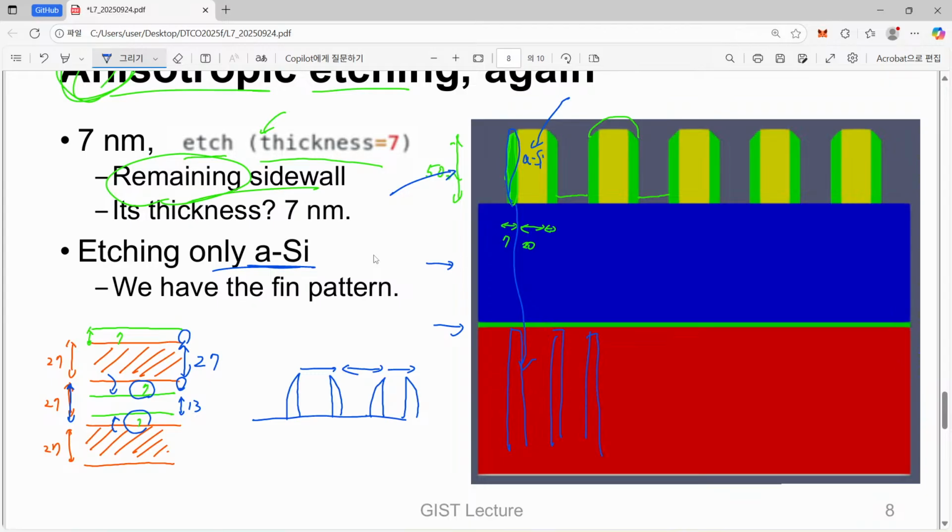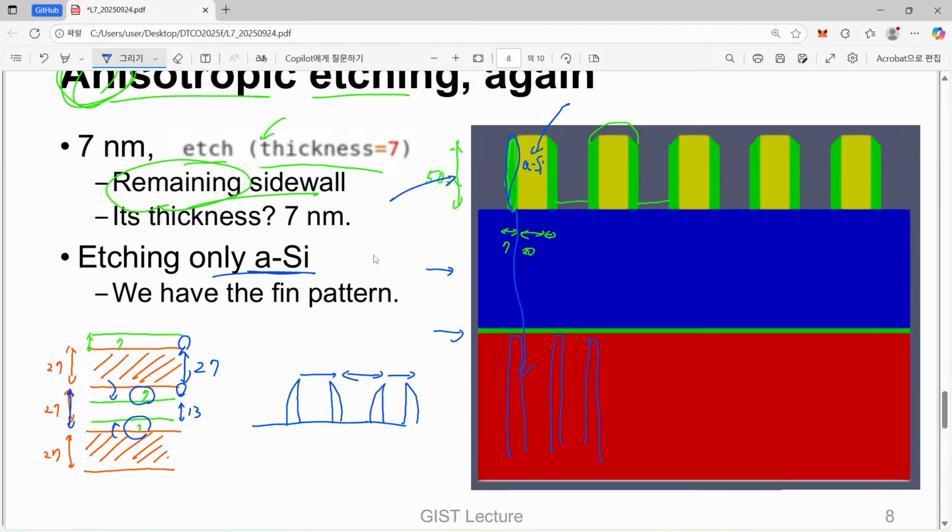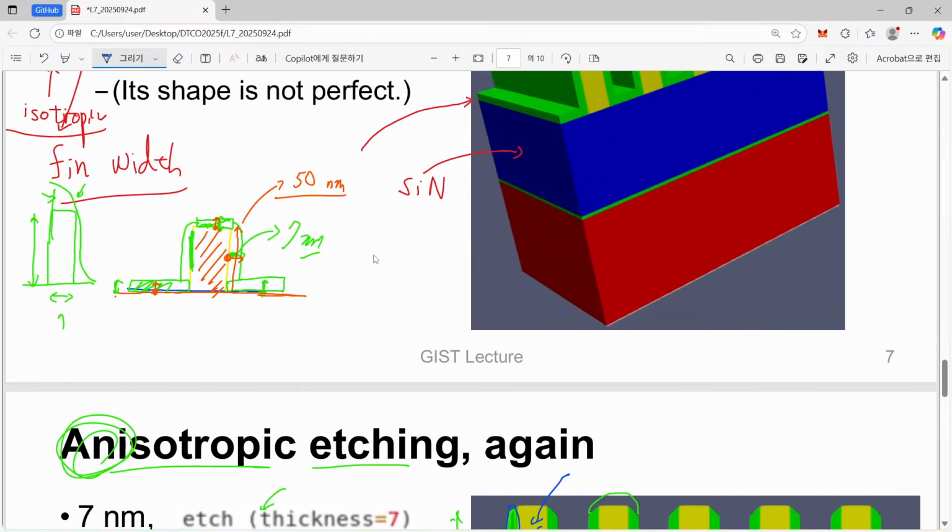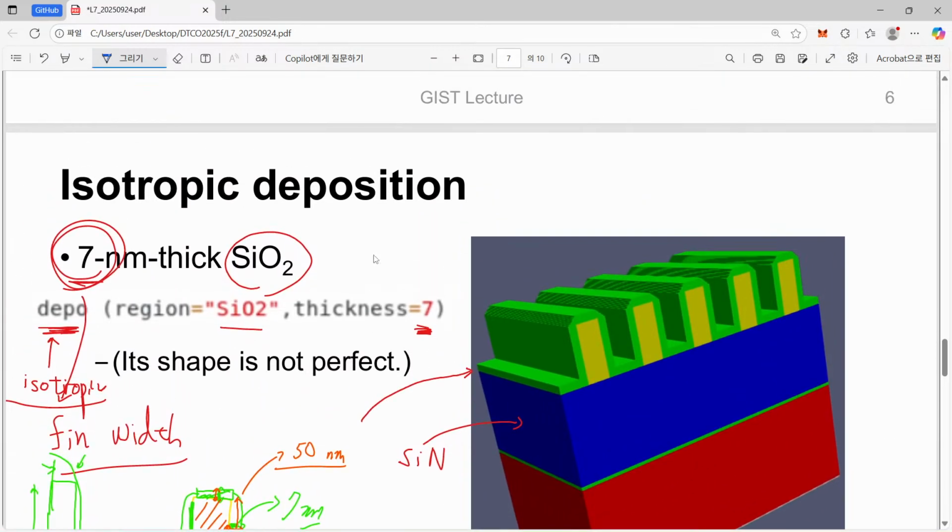So as you know, we have to do once again certain anisotropic etching to realize this shape, but it will take the next lecture. And please note that although we are considering just a part of it, if we remember the layout of our original structure, then we have to have a certain layer where only fins are surviving, and for other parts we have to actually eliminate fins.